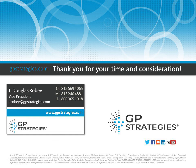Right. So did you figure this out from an assessment, or how did you figure out that it was the training that was wrong and not anything else? A lot of it had to do with downtime of critical equipment in some of their facilities, and then doing the root cause analysis. It was found that they were actually burning bearings up, and when we went through the root cause, this was due to vibration occurring because they weren't installing them correctly and they weren't aligning them correctly. So a quick root cause, which is part of your reliability process, which is great, resulted in, hey, we do have an issue here on the documentation and training side, where you come in and train your people the right way, and going forward, hopefully it reduces defects in your facility.